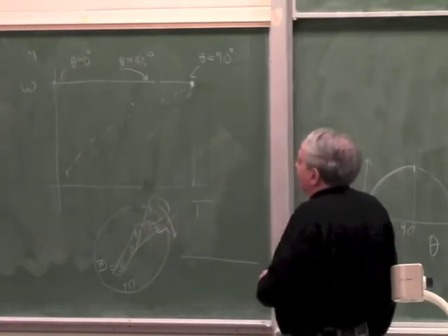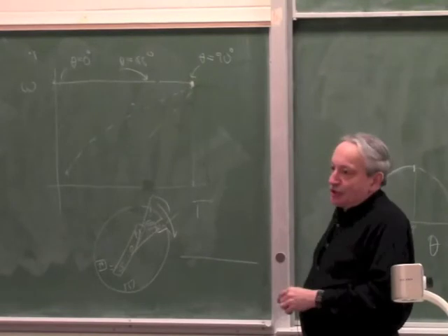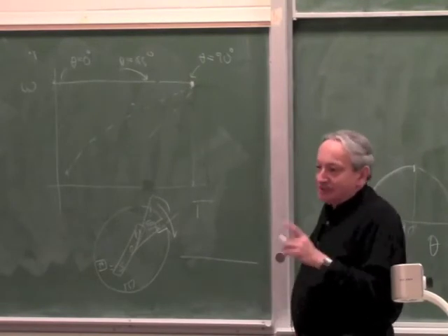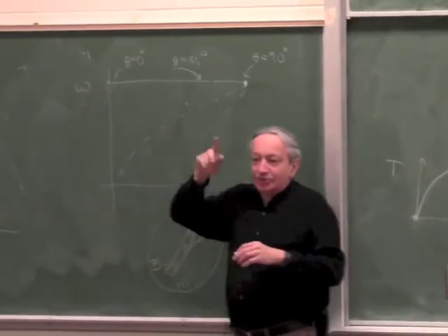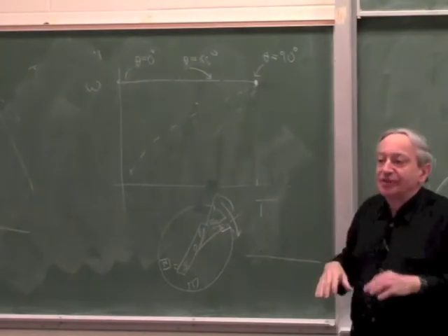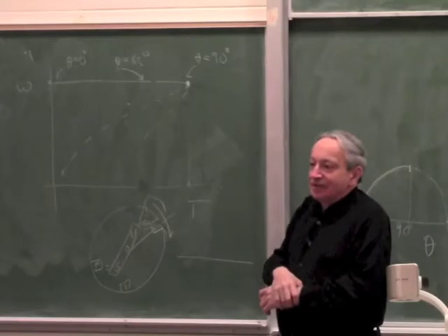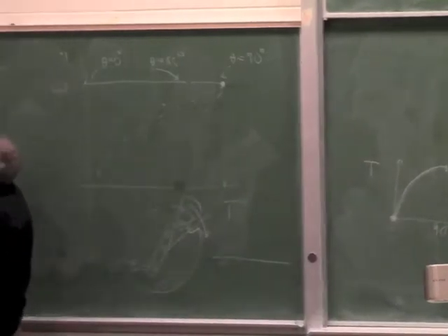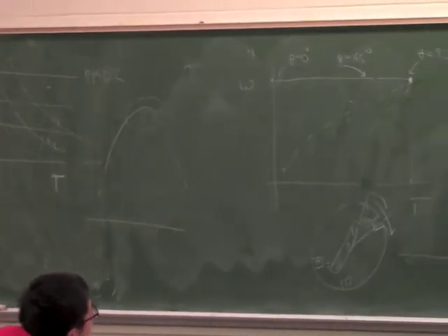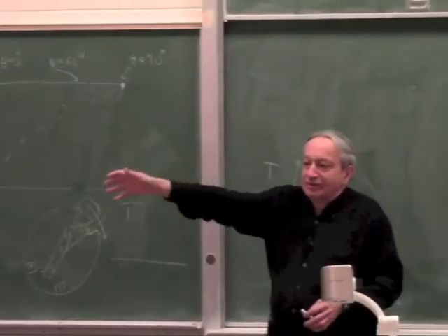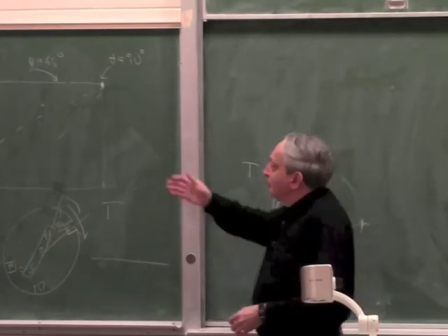Now, if you change the voltage, not the speed. Omega is fixed. Let's keep omega constant right now. It's a rotating field, a constant speed, but you lower the voltage. What will the graph look like? I want to generate an equivalent graph here where I operate the motor on 3 voltages. So if I have an induction motor which is designed to work on 208 volts, like industrial voltage, and I give it 100 volts, what will the graph look like?